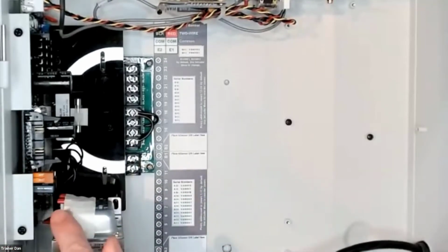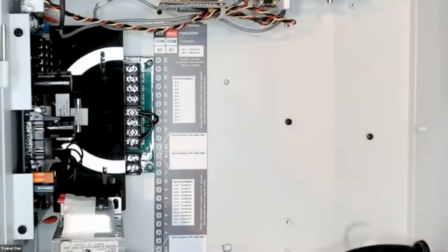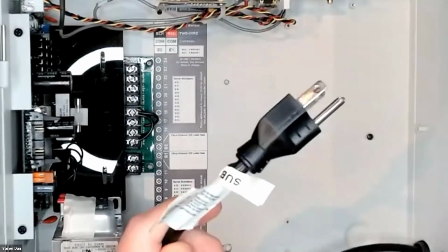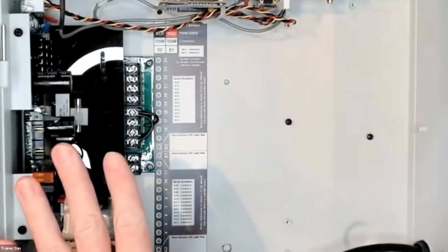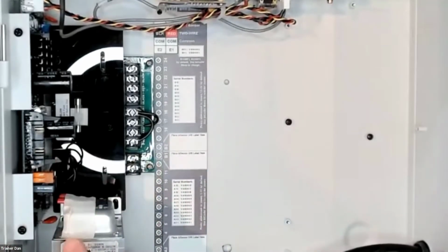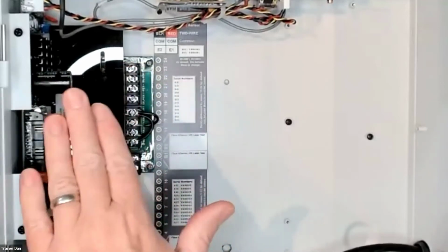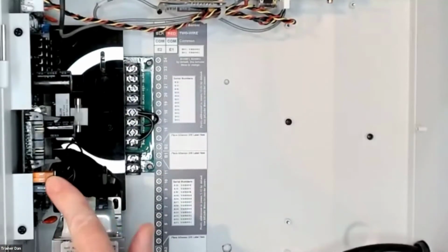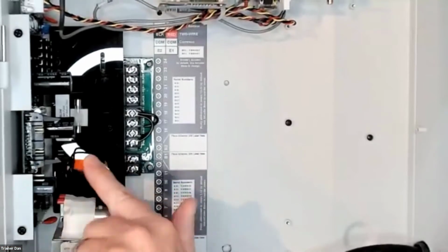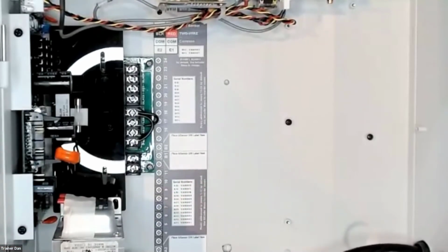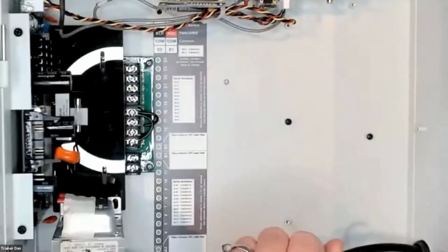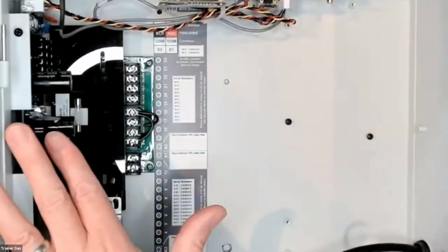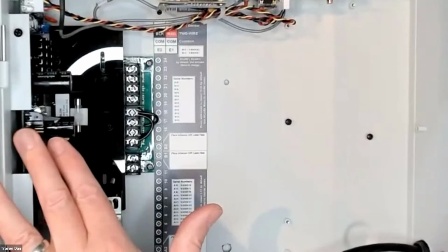So a couple of ways to do that. One is, if you're plugged in, you could just unplug it, wait 5 to 30 seconds, and then plug it back in. That works really well. You could hit the circuit breaker, but I've pulled off my protective cover here, and this little orange lead right here, by unplugging that from those leads, I think is the absolute easiest way. The transformer is still powered up right here, but the power that continues on has been interrupted. So I think that is probably one of the easiest ways to power cycle a controller.